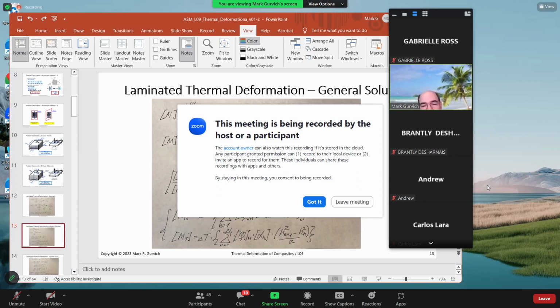And in slang, and sometimes in engineering discussion, those components N sub T and M sub T are called thermal loads. Those are not loads, actually. It's just a function of delta T. But they could produce the same effect. They could generate stresses, strains, and most important, they could produce additional risk for damage.